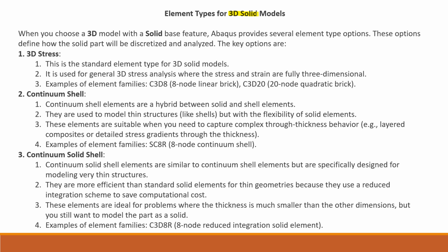Okay, so we want to model a cross-ply plate. We will try to model it using the 3D stress element, purely three-dimensional. This is the standard element type for 3D solid models, and it is generally used for 3D stress analysis, where the stress and strain are fully three-dimensional.